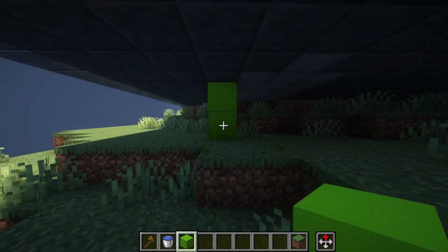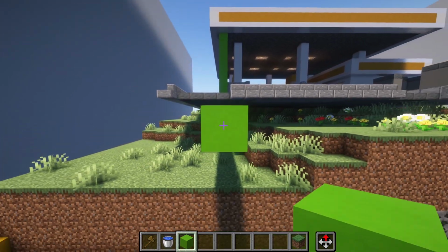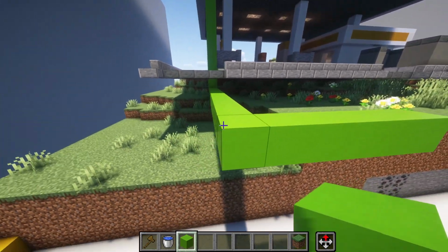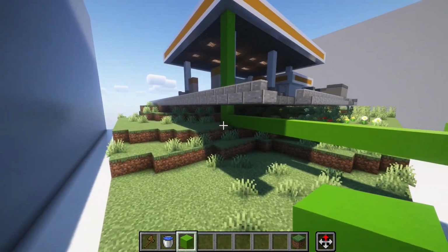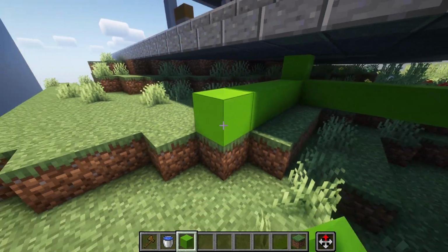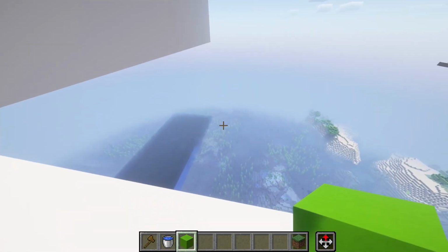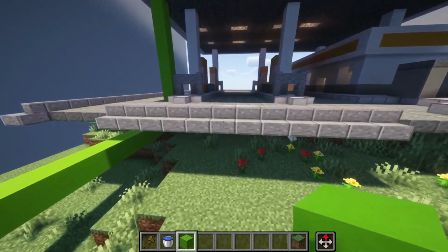But as we touched on in utilities before, this will eventually make its way out into the storm infrastructure that runs along the road, kind of where the curb and gutters are attached to. Or it might make its way out into a retention or detention pond, which will eventually flow into a storm system or into the natural bodies of water around. Same thing with the permeable pavement.